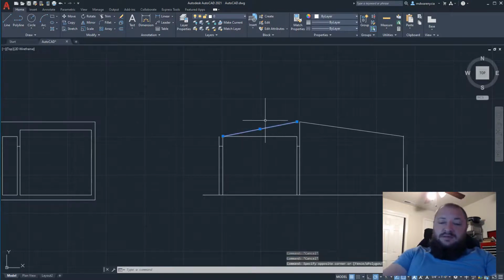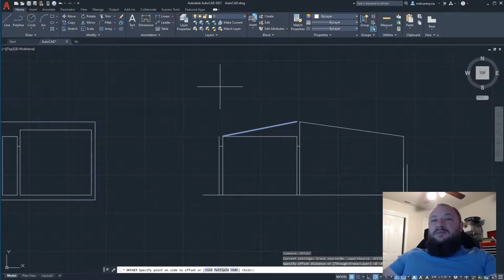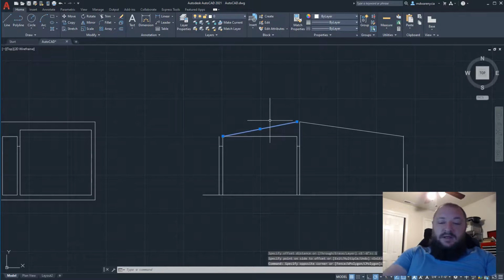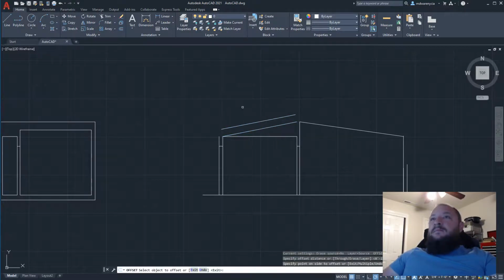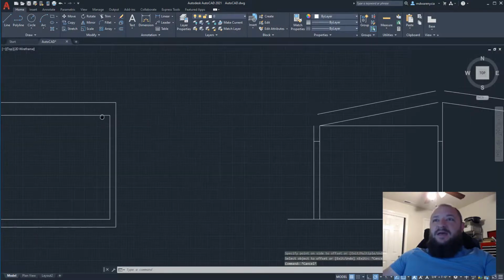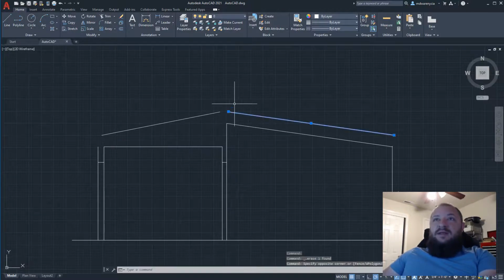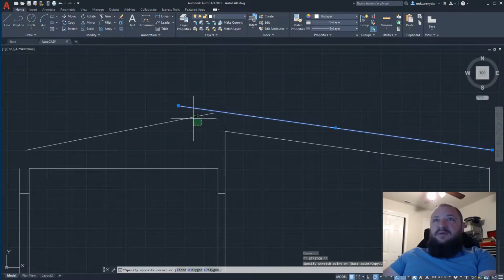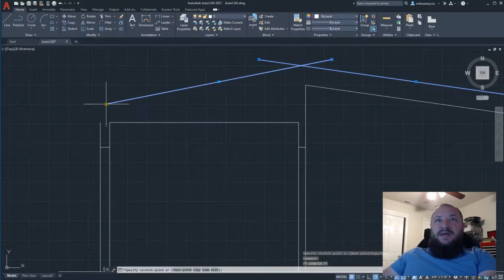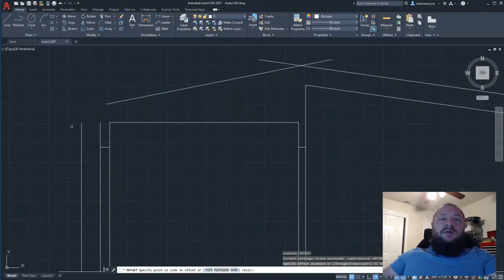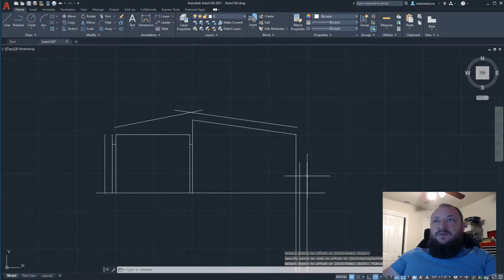so here's what I was doing with that other one with the weird slope. Oops, that was 1 inch offset, 1 foot. So I was kind of guesstimating over here where that height would be. I don't know if it's right there. But what I need is something to show how the roof goes through in this area. And I'm just going to overdraw that. And then each side, I'm going to offset an extra 1 foot here.